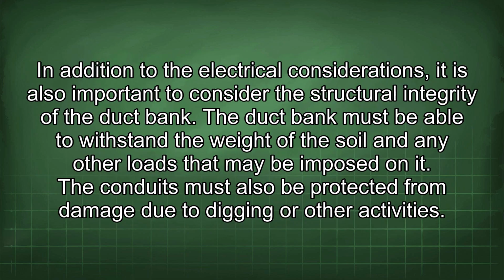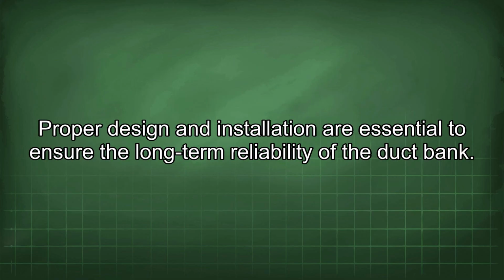In addition to the electrical considerations, it is also important to consider the structural integrity of the duct bank. The duct bank must be able to withstand the weight of the soil and any other loads that may be imposed on it. The conduits must also be protected from damage due to digging or other activities. Proper design and installation are essential to ensure the long-term reliability of the duct bank.